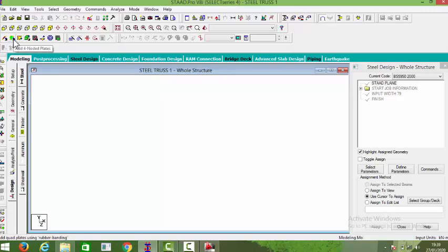And then you have some important tools here, like the add beam tool for adding beams. The add four noded plates for adding plates using 4 points, and then add surface for adding a surface using any number of points. Then add 8 noded solids. You can actually add a solid figure with 8 nodes. Snap node/beam. Insert node. Generate surface meshing. Insert openings in the surface.